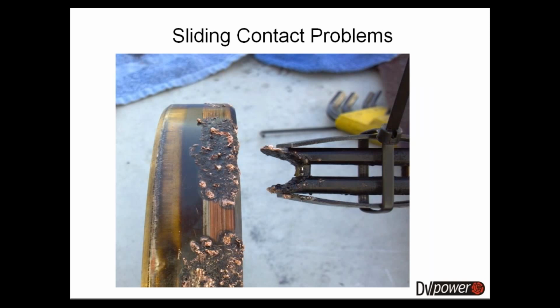And how it looks like in real life is that as this sliding contact became completely worn out, as it operates from one position to the other, it has various types of problems, and all this roughness and bad sliding and bad contact, they all cause the currents of the test to oscillate and to have a strange graph shape.